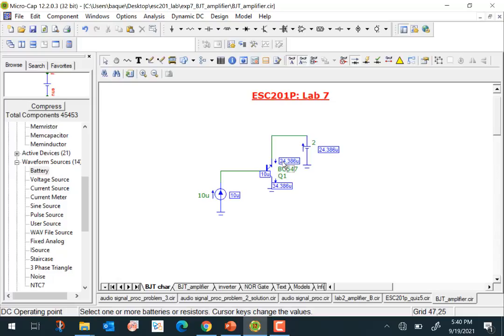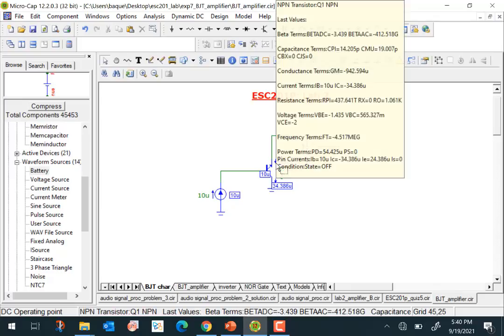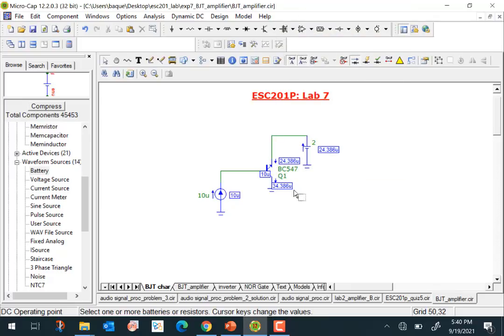The transistor is asymmetrical, and if you interchange emitter and collector, you don't get enough gain. So you have to be careful when using a transistor. You have to make sure that you're using the proper terminals when you make the circuit. All right, so that's the transistor operated in the reverse direction. Let's put it back to the normal mode.